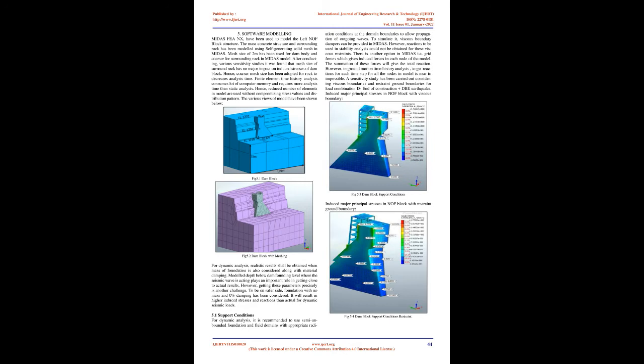Condition: small values of tension on the downstream face of dam may be permitted since it is very improbable that a fully constructed dam is kept empty, and downstream cracks which are not extensive and for limited depths from the surface may not be detrimental to the safety of the structure. It is recommended to limit tension on downstream face to 0.5 MPa. If tension exceeds this limit, reinforcement shall be provided.